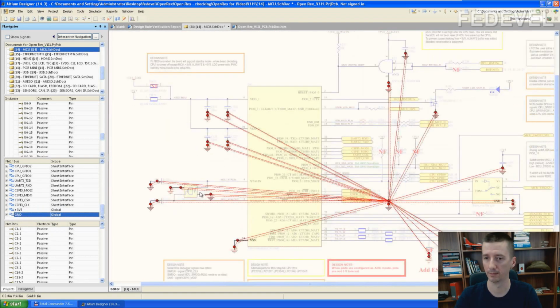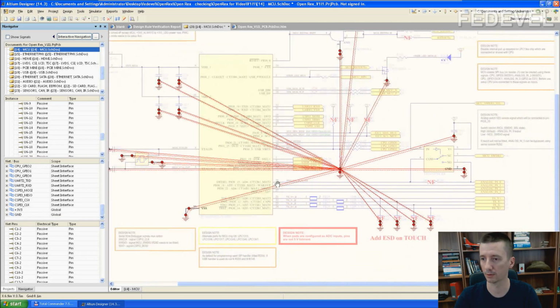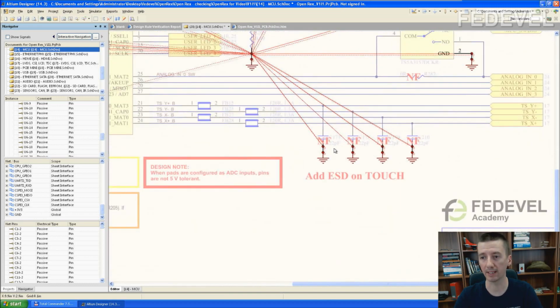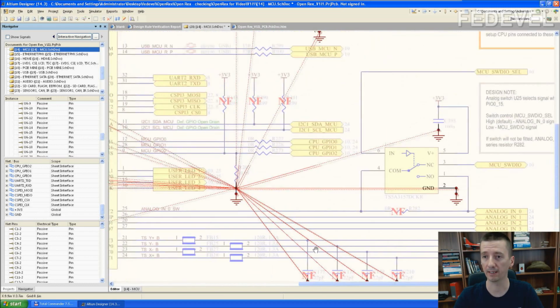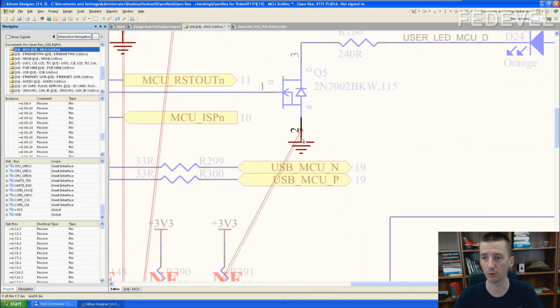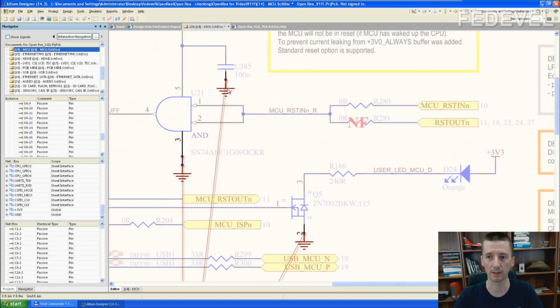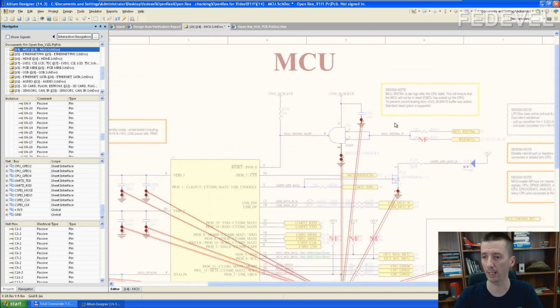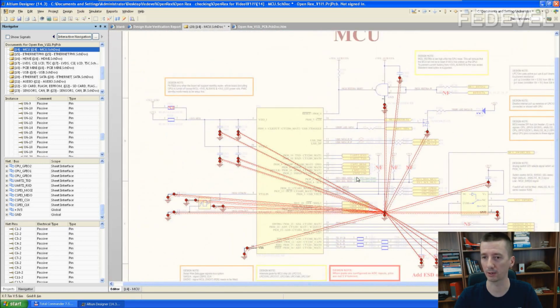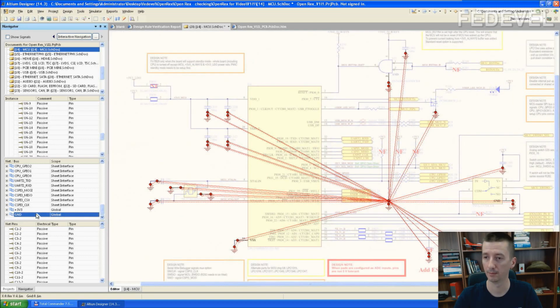And the ground. Okay, the coupling capacitors, ground. I look if there are two dots, and if there is only one, like here, zoom in and be sure this ground symbol is connected to pin. Sometimes may happen that this ground symbol is misplaced and it's not touching the pin. You would notice it when you are doing this kind of schematic checking. Perfect. It looks good.